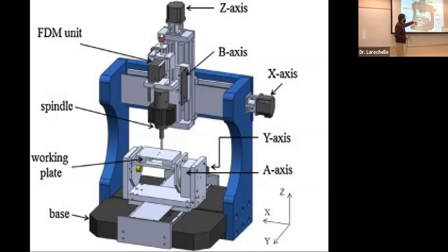So you've got the positioning of the CNC machine tool, which is very precise and repeatable because it's a very nice, stiff kinematic structure. What you don't have, of course, is any rotations. So you're able to do printing along the 3 Cartesian axes, but you're not able to rotate anything in the 5-axis CNC machine tool.